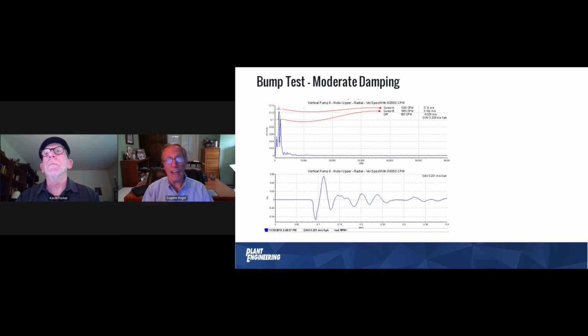So I see a blip, and 5 milliseconds later, I see the peak vibration. That's a phase angle of 180 degrees. But if I see the blip and 2.5 milliseconds later, I see the peak vibration, well, that's 90 degrees. And of course, any other proportion would be any other angle. So it's a proportion of the time between the blips and when the peak vibration occurs. Hope that explains it.